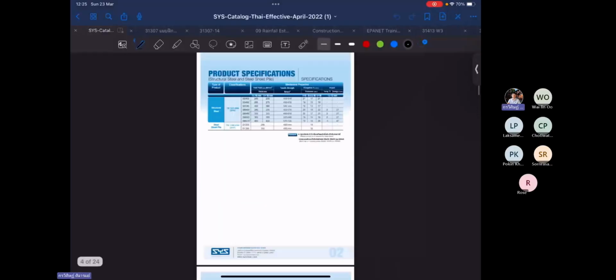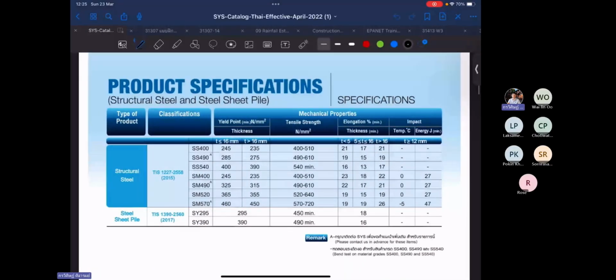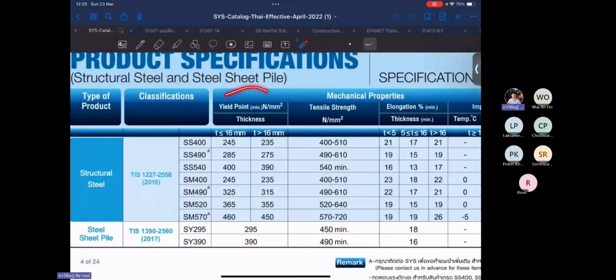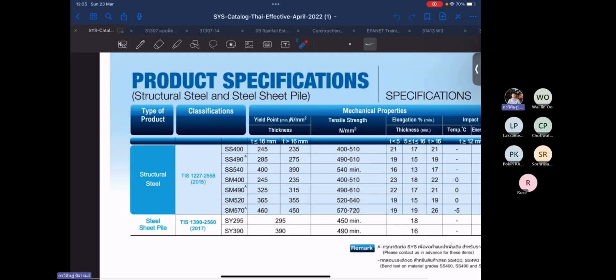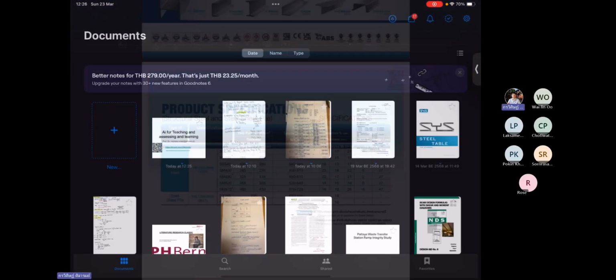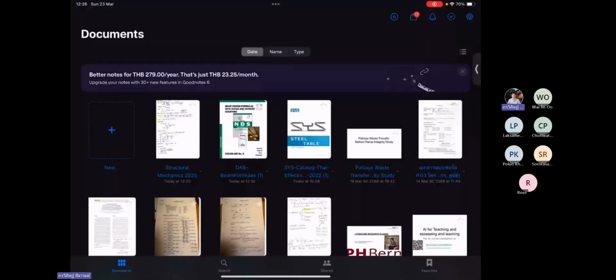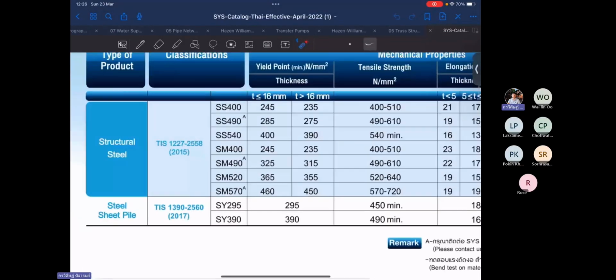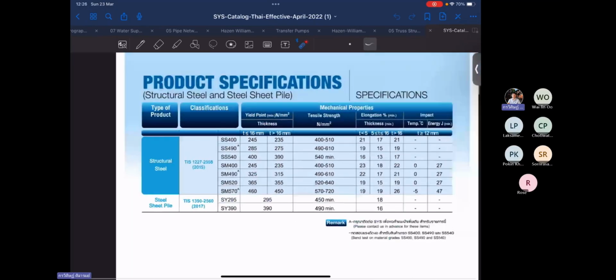In the catalog, there will be the spec of this yield strength. There are many grades, so we as a designer select the grade we would like to use, and then we compare it to the design. Okay, let's use the cheapest one, SS400. So the yield strength is 245 Newton per...